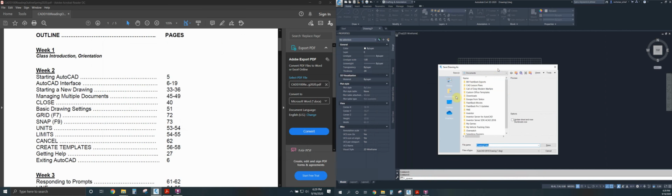That will save it, and let's just say desktop, and we'll call this test. And right here where it says AutoCAD 2018 Drawing (*.dwg), you will change that to AutoCAD Drawing Template (*.dwt), and for whatever reason that likes to change the location.